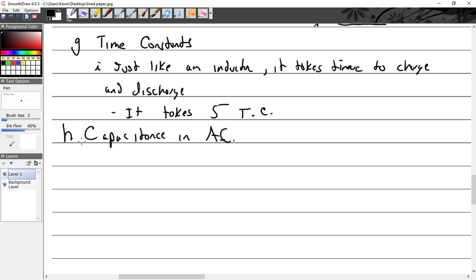All right, so it's important to note, if I have a capacitor in series in a DC circuit, the series DC circuit is going to see a capacitor as a what? Opposite of a short, an open. So if I take that theory and I put a capacitor in series in an AC circuit, is it still an open? No. It is not.